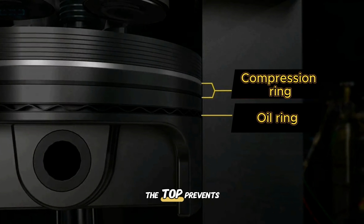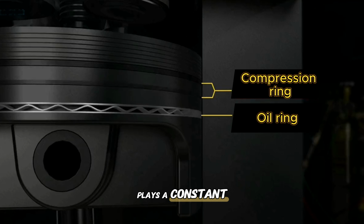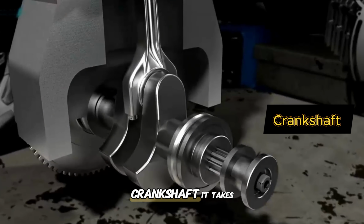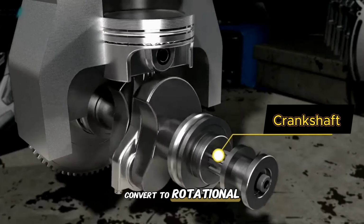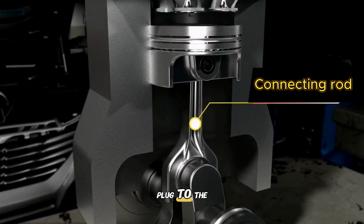The ring at the top prevents smoke from flowing downward. The second ring prevents oil from flowing into the combustion chamber. The third ring plays a constant role in transferring oil, applying it to the inner wall of the cylinder. This is the crankshaft. It takes the linear motion of the piston and converts it to rotational motion. The connecting rod connects the piston to the crankshaft.